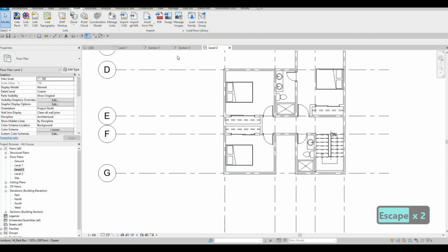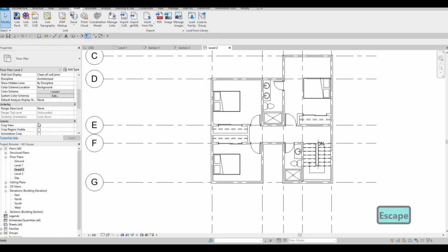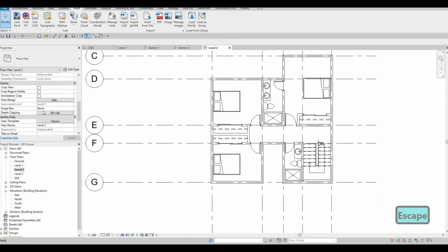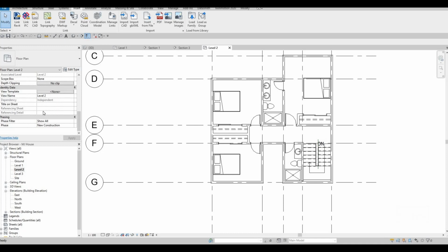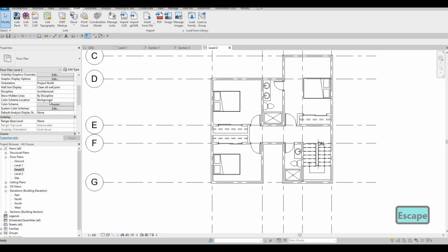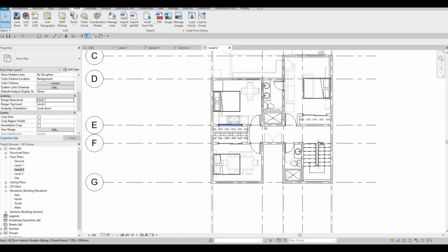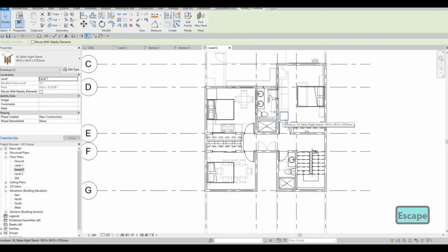And then obviously we're not yet done. Let's load in, or I'm gonna check the underlay. Maybe we already have that table, side table. So go to underlay, change this to level 1, and yes, we have the nightstand right here.